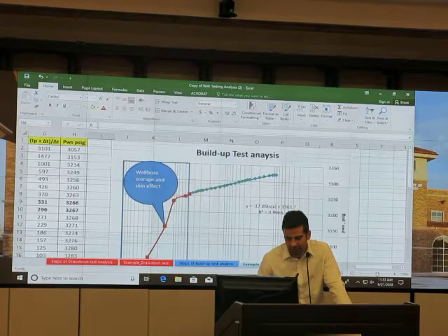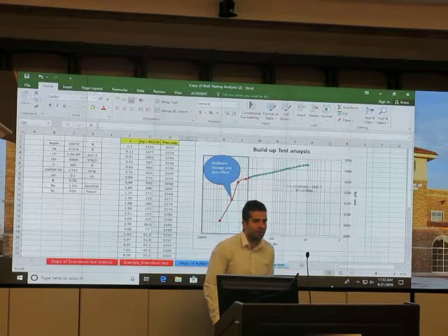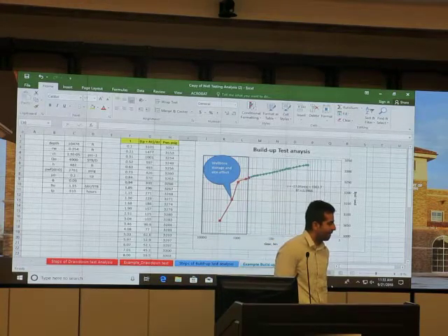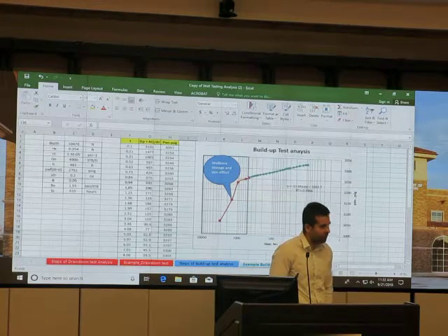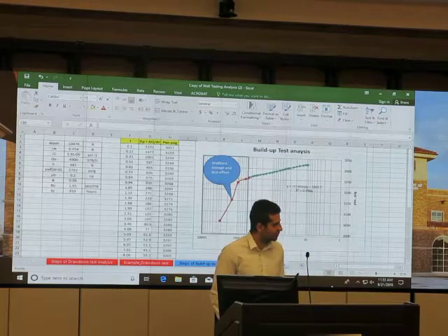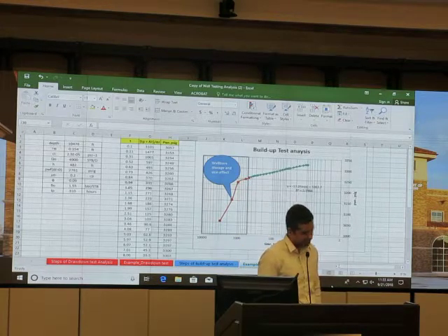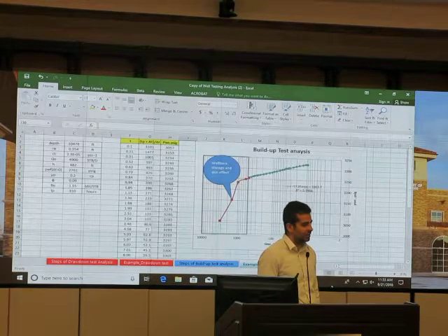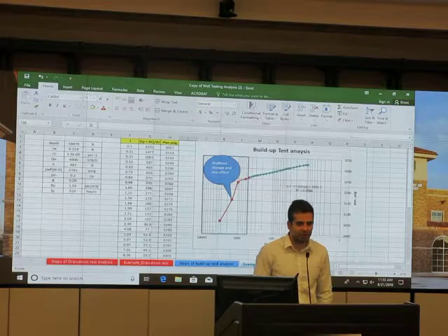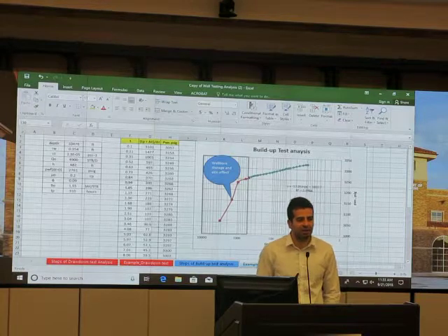So let's talk about build-up. What is build-up? When you close the well and the pressure builds up. And what information can we get from it? Like the drawdown test, you can get permeability, skin factor, and you can get the PI.